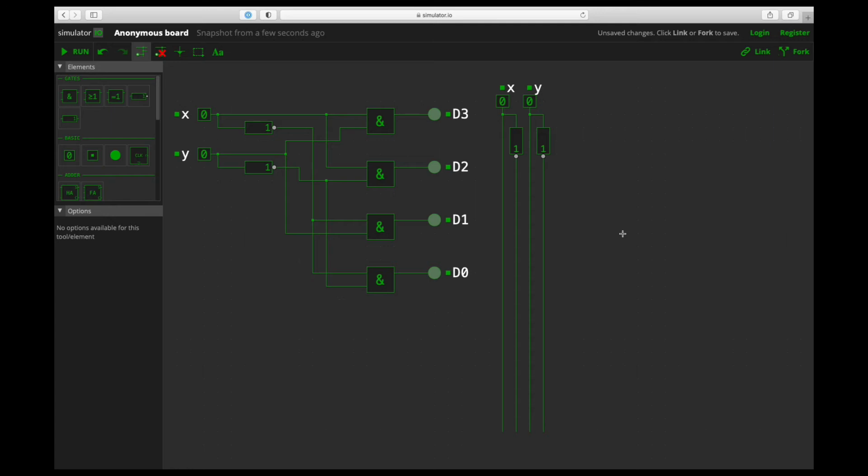So, and if we look back at the truth table, we can now see that we can directly build our gates as the sum of products, because remember, then we have the sum of products. The output is true when any given one of the product terms occurring in the sum is true. So in our particular case, the truth table reflects that relatively nicely, in that in the sum of product terms we only have one entry that actually does that.